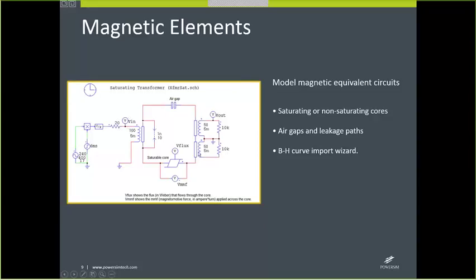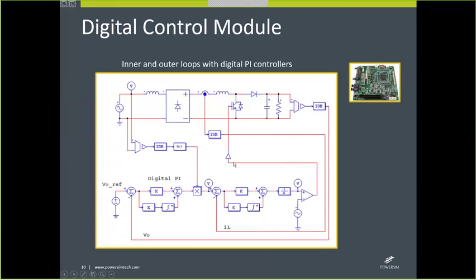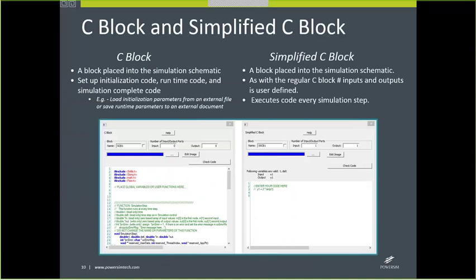Or if you wanted to have more complex windings over here rather than just 50 turns with 5 milliohms of impedance, you could add an RC network and have fewer windings. Like maybe one winding with an RC network connected 50 times in series instead of having just one big 50 turn winding. It's up to you really to figure out what the best way to model your particular system is. Oh, I seem to be skipping a lot of slides.